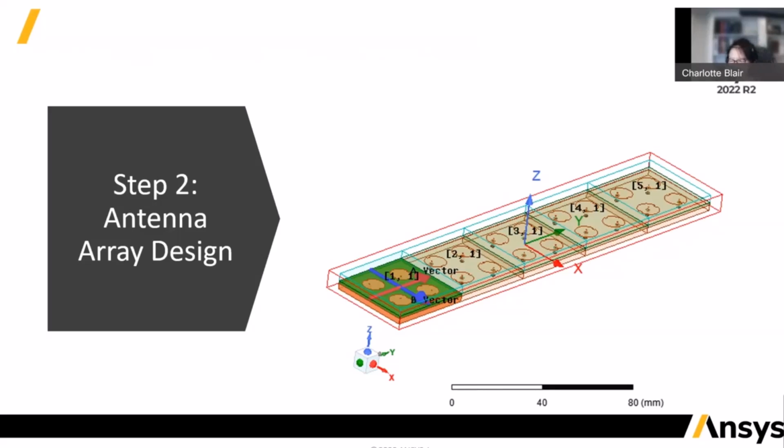And you can say, yes, oh, so what's that going to do? Well, when we create a 3D component and we use the finite array wizard, not only are we efficiently creating the model geometry, we are also going to efficiently simulate that, because we can reuse the mesh of this component as we created the array. We'll simulate the whole thing, but we have a start mesh. We know from this unit mesh where we started, and we have the idea of reusing that mesh. So why does that matter? We don't have to start all over and remesh every single element in that array and times that by 100.